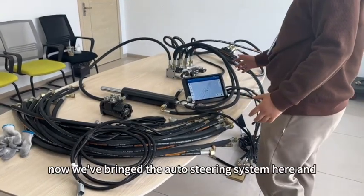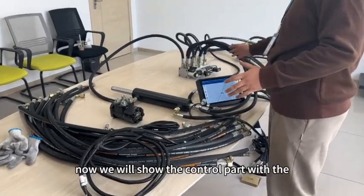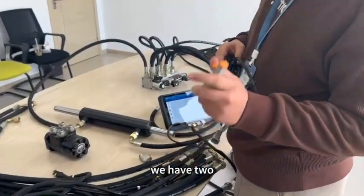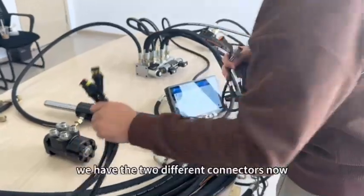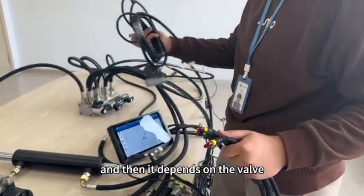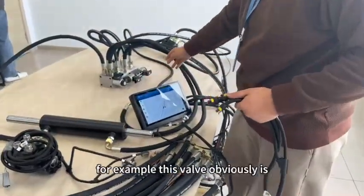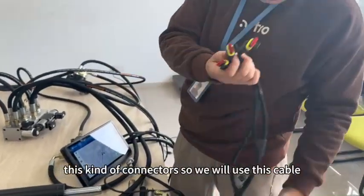Okay, hello guys. Now we bring the auto steering system here, and now we show the connection part with the electric valve. First, we have two kinds of cables. You can see it's a little bit different, but we have two different connectors. And then it depends on the valve. You can use this type of connector or this type of connector. For example, this valve obviously uses this kind of connector, so we will use this cable.